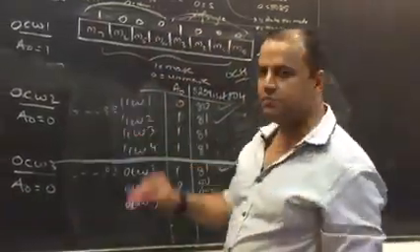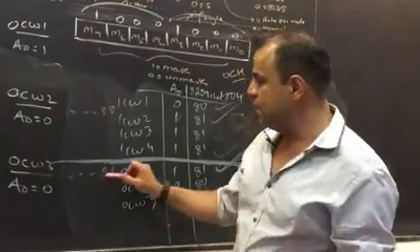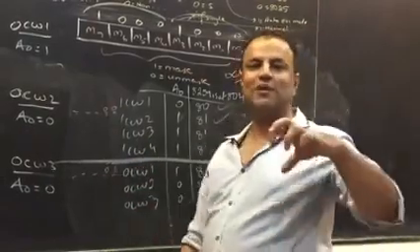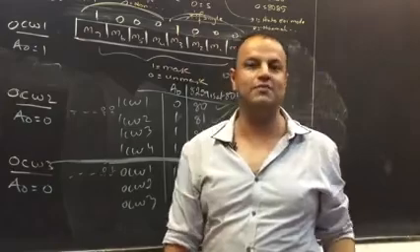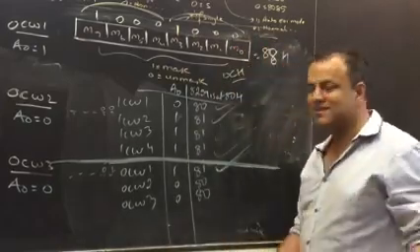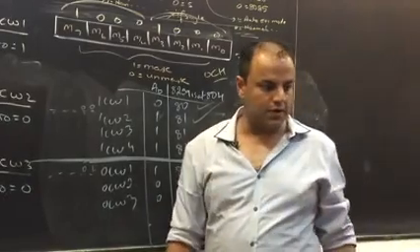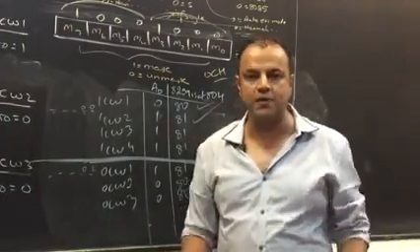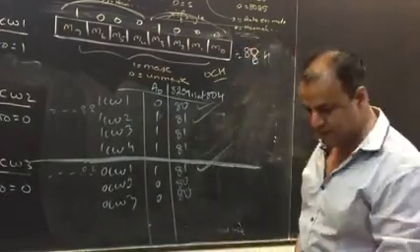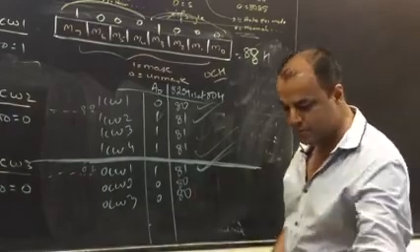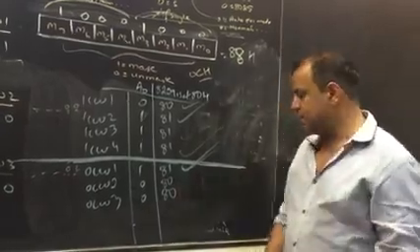If the fourth and the fifth bit are 0, 0, it's treated as OCW2; 0, 1, it's treated as OCW3. That's why they have fixed patterns. I told you the reason will come back and will hit you very hard. See how wonderful all this is. This is not like one night somebody thought of it, okay, let's do this. This is made out of tremendous logic, and that's how all these chips are made. Every chip you learn, if you understand them properly, you get mind blown by it.